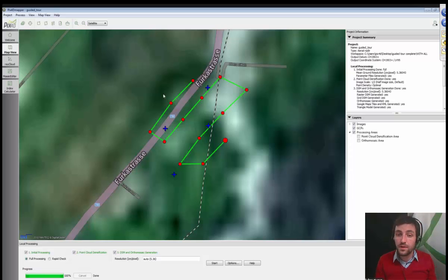I'll give you two examples. The first one is, locally you could generate a project, everything could go well, everything seems reasonable. However, the elevation model for some reason was not perfectly flat, but was slightly tilted. It would be very difficult, if you just look at the results in a GIS software, to see that there was a tilt in this elevation map. And if you then use this elevation map to, for example, build a house, you may end up with a tilted house, which is probably something you really don't want to have. So it's extremely hard to know, even if the whole elevation looked reasonable and you could see details, if it's slightly tilted or slightly bent, which has big consequences when you then use it to do real work.